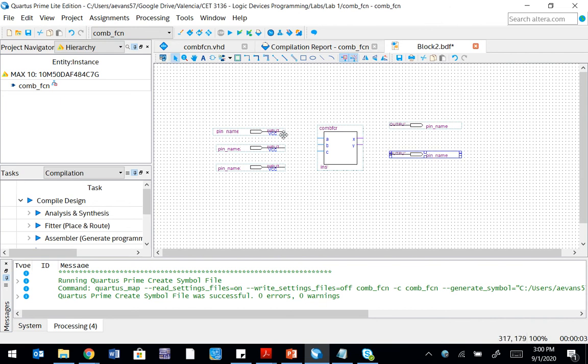And we're going to connect each one of these directly to each input that you see on the screen. Same thing for the outputs. All right, so we've got those connected. Now each one of these is eventually going to represent a certain pin or a certain location on your PLD. Right, now we're going to give each one of these a name.